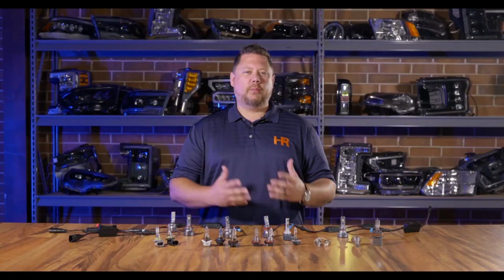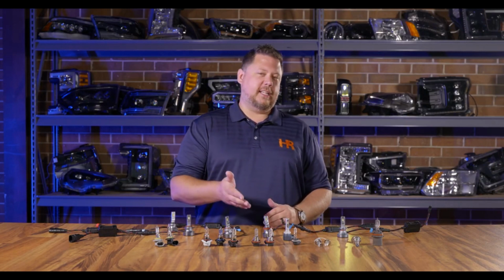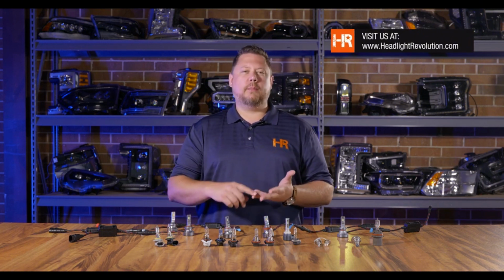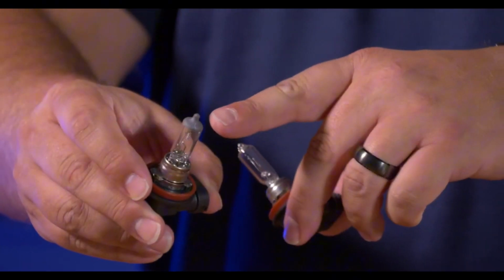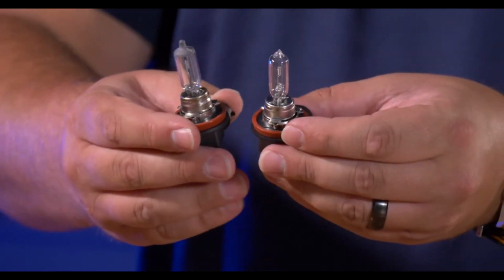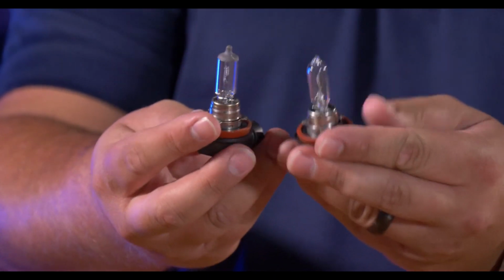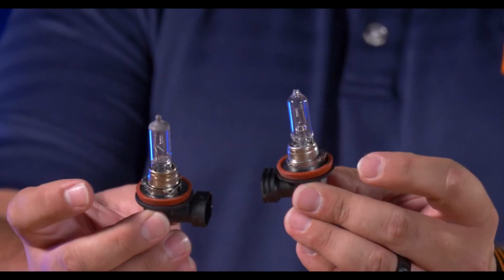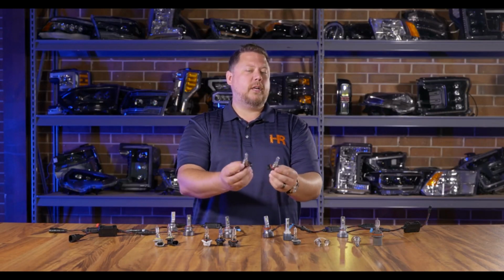Another example of similar bulbs with totally different names that an aftermarket bulb fits both is H8, H9, and H11. If you have any of these light bulbs, they fit your fog light, low beam, and high beam. An H11 LED bulb or HID bulb is going to work. We're talking about these ones in front of me. You have the H11, which is the more common style with the little painted cap, and an H9 without a painted cap. But everything else about them physically on the outside is the same. They have the same type of filament, the same mounting points, the same O-rings, and the same connectors. So other than the brightness, they're pretty much interchangeable.